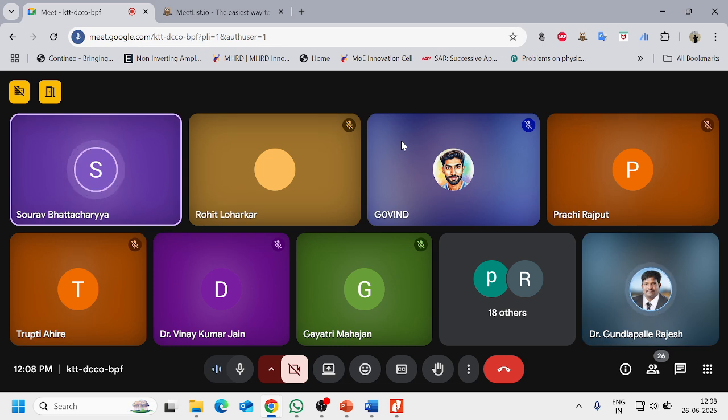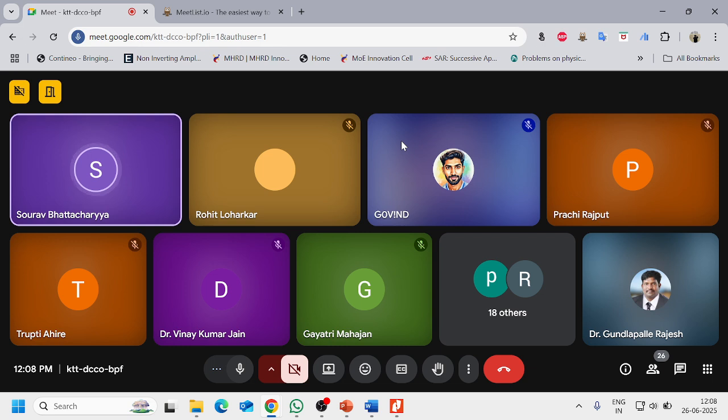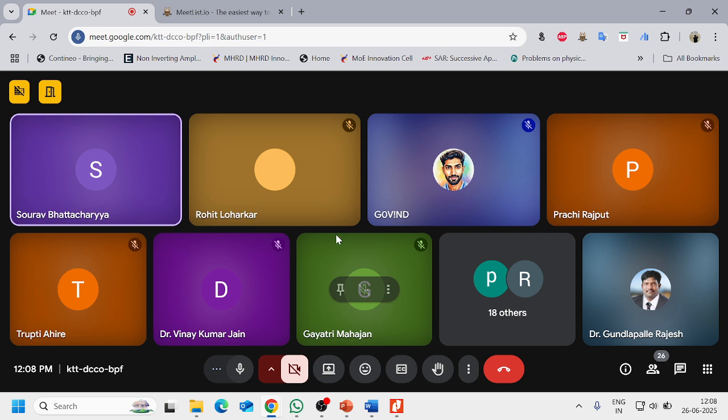But the only thing is, when we implement in real time, the sensors will not work actually. The prototypes the students use for projects work on 5 volts only, whereas in real time you don't require 5 volts, you require 24 volts. This 24 volts can be controlled with Arduino boards. They will not provide it, but they can control it.